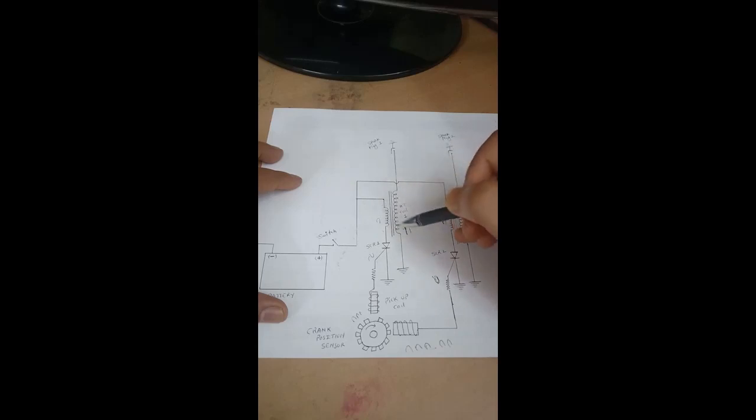There is no drop of voltage due to distribution, as there is in the other battery coil ignition system or CDI ignition system. There is a drop in voltage there because there is a distributor. That is, there is one high tension coil, and only that one coil distributes high tension voltage to all 4 cylinders or 2 cylinders.